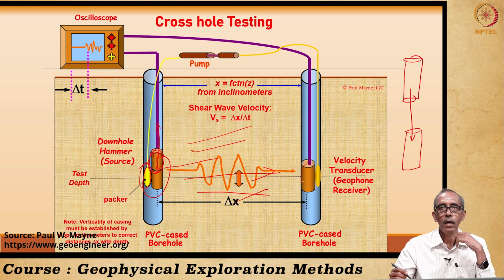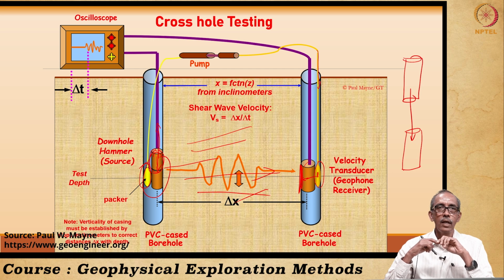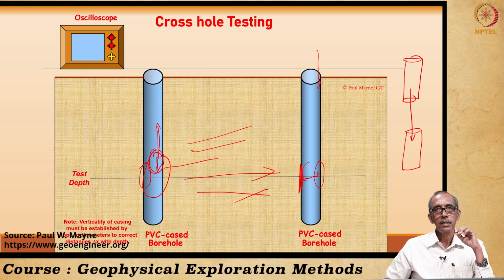geophone. The geophone also has an inflatable packer system. With the help of this packer, that means we pump in some gas or air, this will inflate so that the geophone firmly touches the wall of the well. So, this is the special arrangement that is necessary to carry out borehole cross-hole seismics, right.